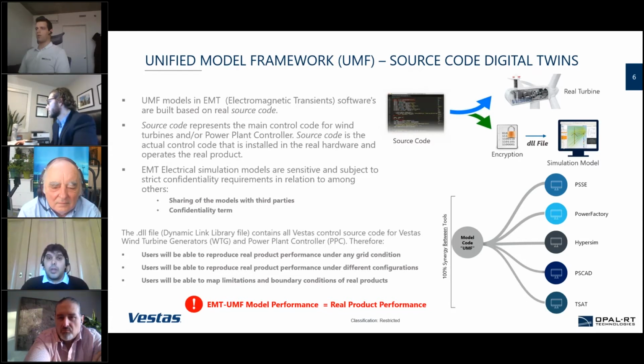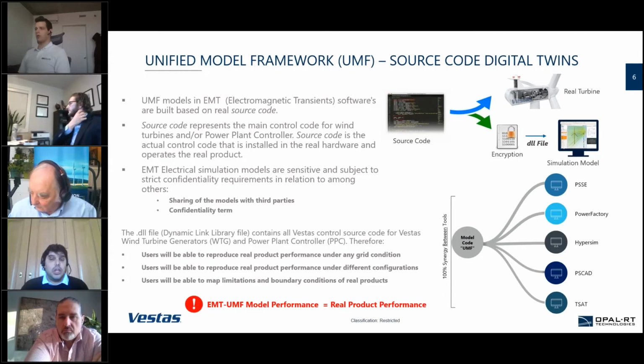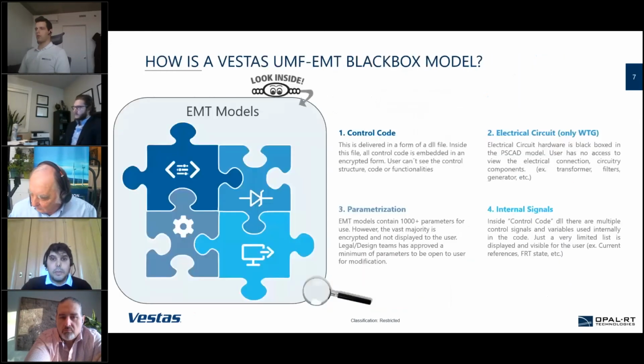This is the only way we have to cope with the current challenge of the high penetration of inverter-based technologies. When we are dealing with weak grid projects, unbalanced faults, and series compensation, and we need to determine how to tune the protections of a wind farm, the only way to achieve that is with a source code integrated model that accurately represents the controls of the real plant.